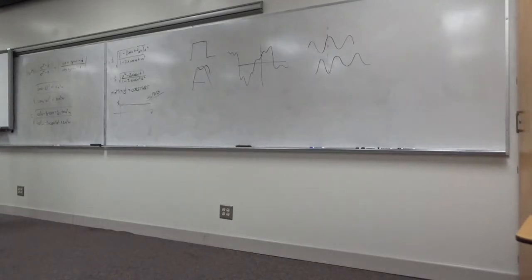Why would we do something like that? There are a couple of reasons. One reason is if the gain response is just a constant, the gain's not doing anything. So what must we be working on? Phase, right? And so if you have some kind of a phase shaping filter, now why would you have a phase shaping filter? To remove phase distortion, for one thing. Okay? If you have a phase shaping filter, you're wanting to massage the phase in some way. And by saying we want to change the phase, I'm implying, but not the amplitude. This won't change the amplitude.